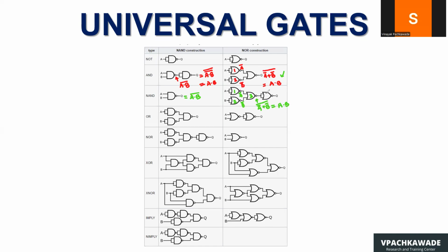Now A and B is the input to gate number 4, actually, because both inputs of gate number 4 are shorted. Therefore, the output here, Q, is equal to A NAND B, simply. So you see, we got the NAND implementation done.